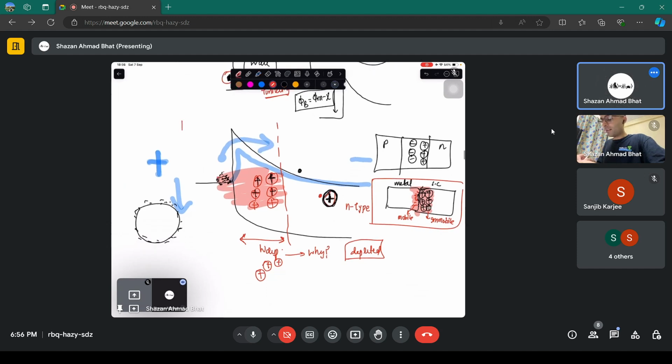You remember the distribution of electrons? That is applicable every time. That is the general concept. The distribution of electrons is the same in metals too. Although in metals it is the Fermi function times the density of states, it is the same concept in metals and semiconductors. Now there are so many electrons present near the Fermi level here that when you lower the barrier, the blue curve, electrons will go to the other side.